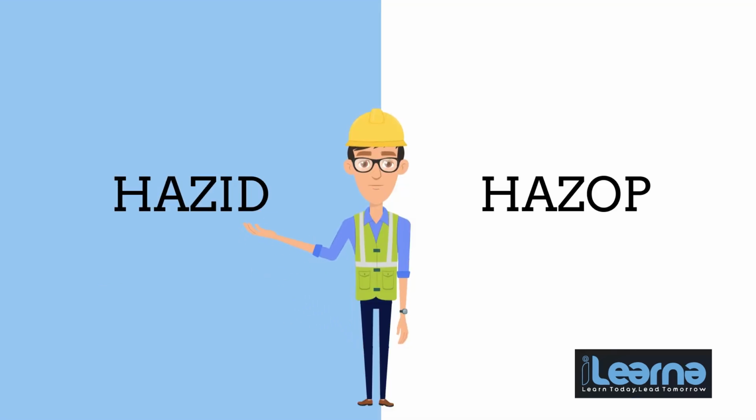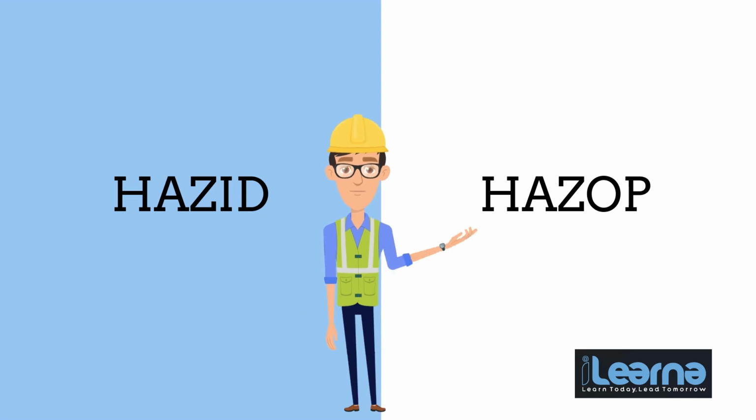In summary, HAZID is typically used at very early project stages to provide a generic view of potential hazards across the entire plant. It helps identify all generic risks and ensures that appropriate safeguards are in place. On the other hand, HAZOP is applied later in the project to define in detail and mitigate risks associated with specific process equipment and operational parameters and activities.